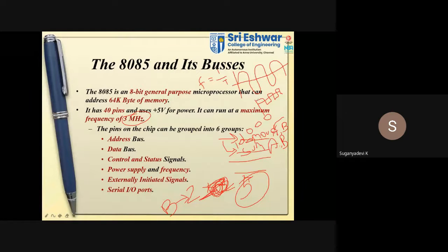The first instruction will be executed in the first clock pulse. We have started the pipelining operation, right? Fetch, decode, execute and write. Four operations, four clock cycles. Do you remember all that? These four operations will be performed in a pipelining structure and require four clock signals.